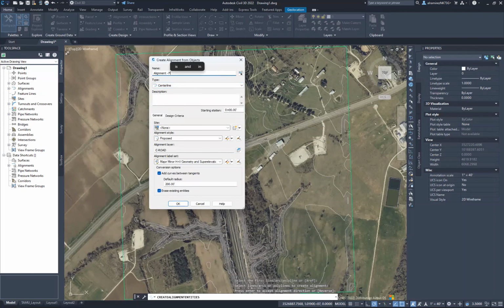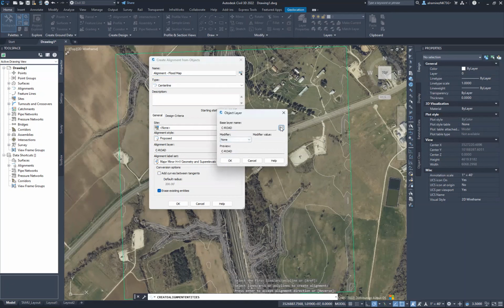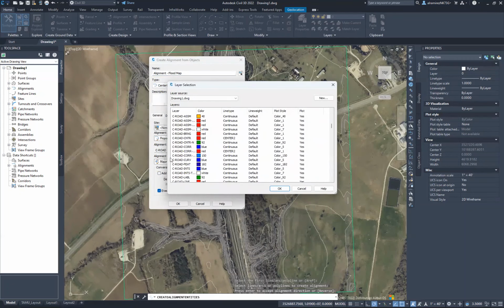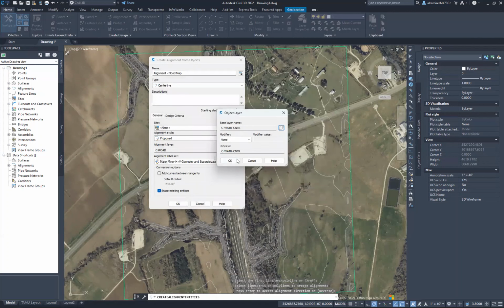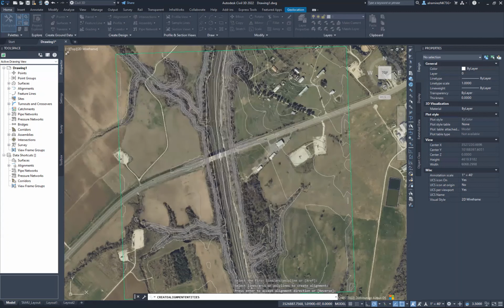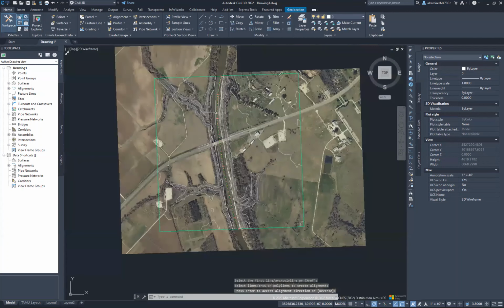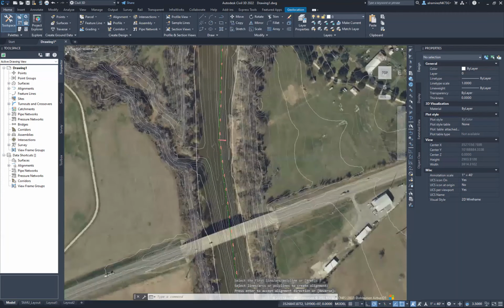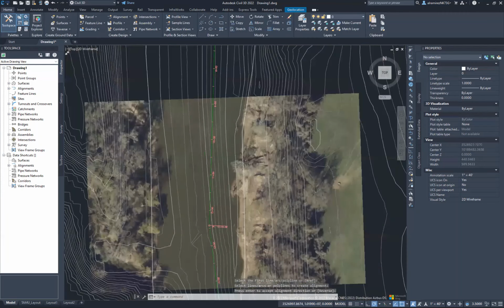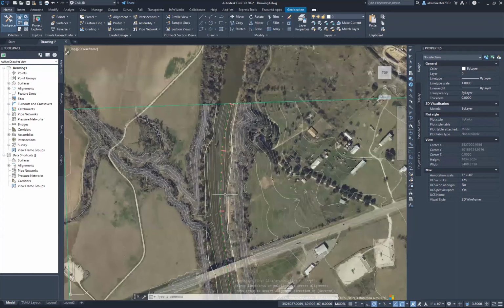You can name this whatever. I just named it flood map. Click that. Change this layer just for consistency purposes, because it's obviously not a road. We're gonna go to water and then center for water center line. Now notice that we have station numbers on our river.